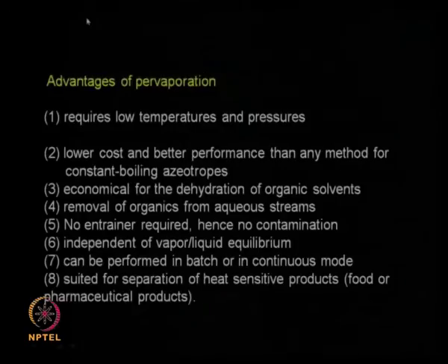You will be adding an adsorbent like a silica gel or alumina or zeolite. It will absorb all the water present in a solvent, and then you will do a filtration. Now this silica gel or alumina will contain water, so you may have to take it to a heater and heat it, so the water gets vaporized, the silica gel is again available, you can take it back again for adsorption. So you see there are so many extra steps, it is going to add to the cost, whereas pervaporation is going to be very economical for dehydrating organic solvents.